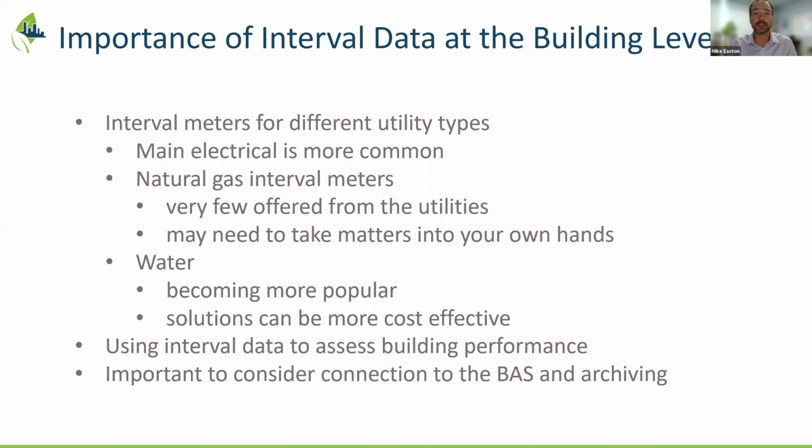And obviously there's some labor necessary to connect that to an energy management platform. One caution, though: there are a few different meter manufacturers providing building level water metering across the country, and with some of them, the pulse outputs are very difficult to integrate, even though it says pulse output. In some cases, you're getting really high readings, up to 1,000 pulses a second. That might not be possible for an energy management system or a data logger to collect accurately, so you need to verify that before the installation is done.